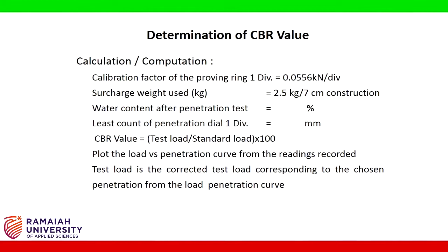Plot the load versus penetration curve from the readings recorded. Test load is the corrected test load corresponding to the chosen penetration from the load penetration curve. The results of CBR value for 2.5 mm penetration and for 5.0 mm penetration are presented.